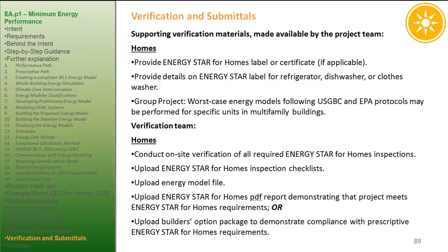Verification team. Homes: conduct on-site verification of all required Energy Star for Homes inspections. Upload Energy Star for Homes inspection checklists. Upload Energy Model file. Upload Energy Star for Homes PDF report demonstrating that project meets Energy Star for Homes requirements, or upload Builder's option package to demonstrate compliance with prescriptive Energy Star for Homes requirements.